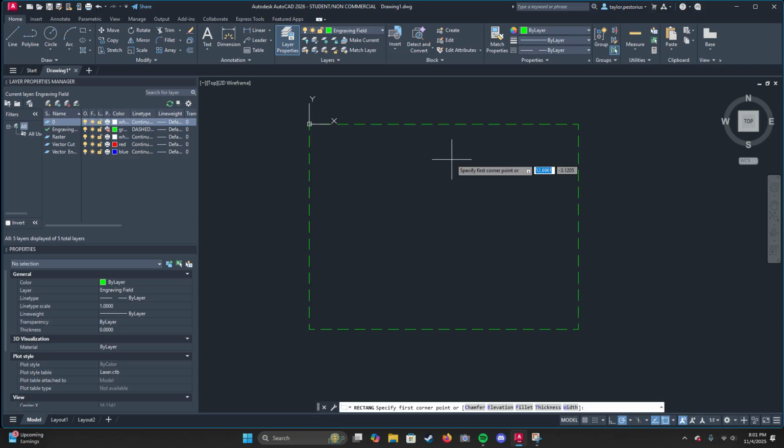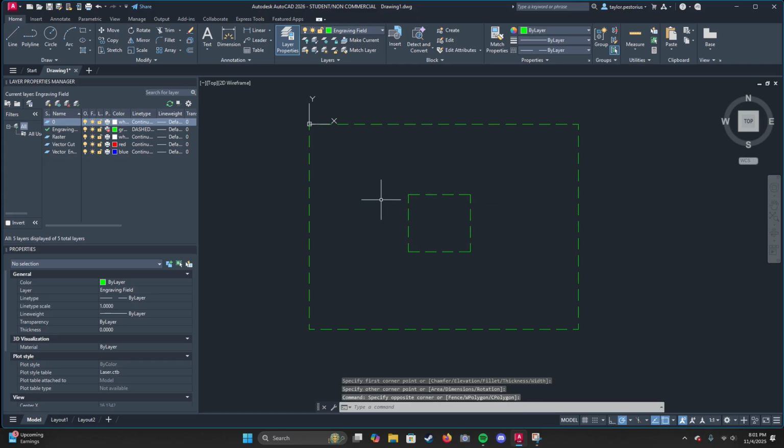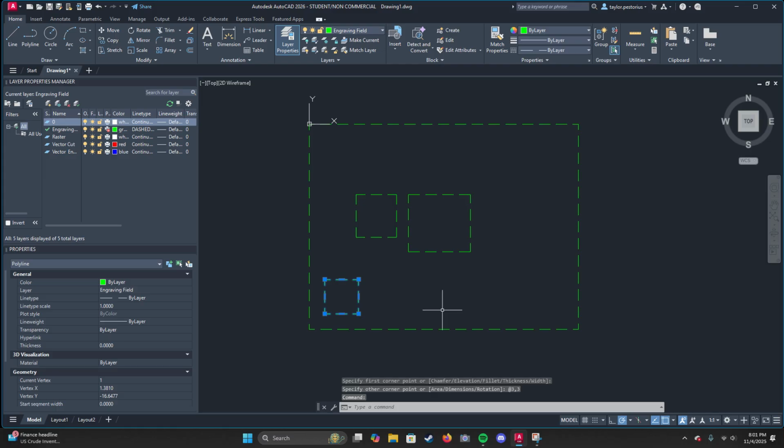The other thing that I want to mention, if you are to make two rectangles, you can make the first one by going up to your draw, and you'll have this. It may be in a different place, but your draw tools are what we're going to use. They're very important. And you can just hit rectangle. You can specify your first corner, and then you get two boxes here. I can type in exact dimensions that I want here. The way I get from the first dimension to the second dimension is by hitting comma or hitting tab, and that'll get you to the second dimension.